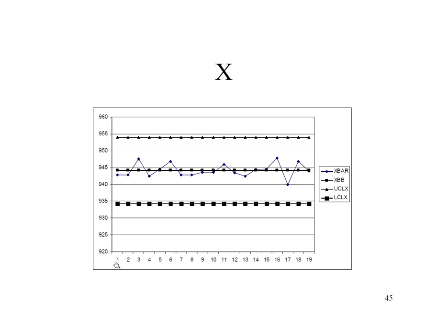So now we have one point that isn't position one in the boat, it's run one, where you cleaned the wafers, loaded them, grew the oxide, took it out and measured it, right? Every wafer in that run. And so that would be the mean of each run. Okay, some days it's up, some days it's down. And then you can use these upper and lower control limits to make decisions about whether it's in control or not. And that's a later talk.